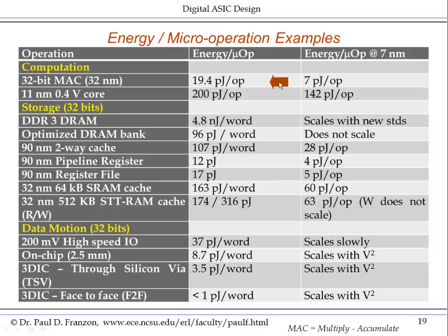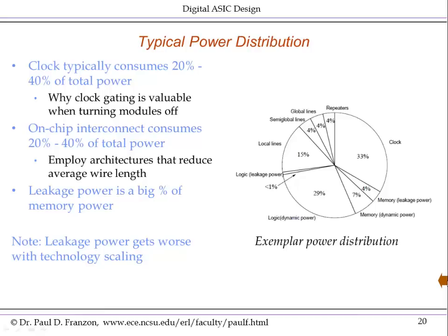So there are actually dramatic differences in terms of how you organize your data, how you organize your data flow, how you structure your design, and what algorithm you use even, that can make a huge difference on power consumption if you consider these sorts of issues, and possibly you can do some enabling calculations while doing design. And frankly, I'd encourage you, if you're working in a power constrained environment, to develop a table like this and actually use it while you're doing design. And again, this is exactly what we do in our research work on low power logic.